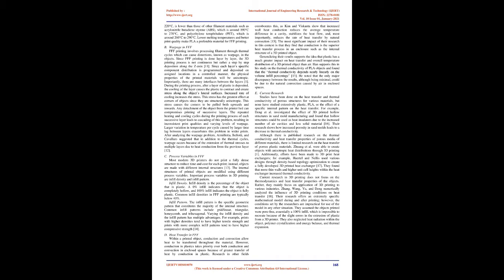During the printing process, after a layer of plastic is deposited, the cooling of the layer causes the plastic to contract and create stress along the object's lateral surfaces. Increased rate of cooling increases the stress. This stress has the greatest effect at corners of objects since they are structurally anisotropic. This stress causes the corners to be pulled both upwards and inwards. Any detachment of the object from the printer bed can compromise printing of successive layers.